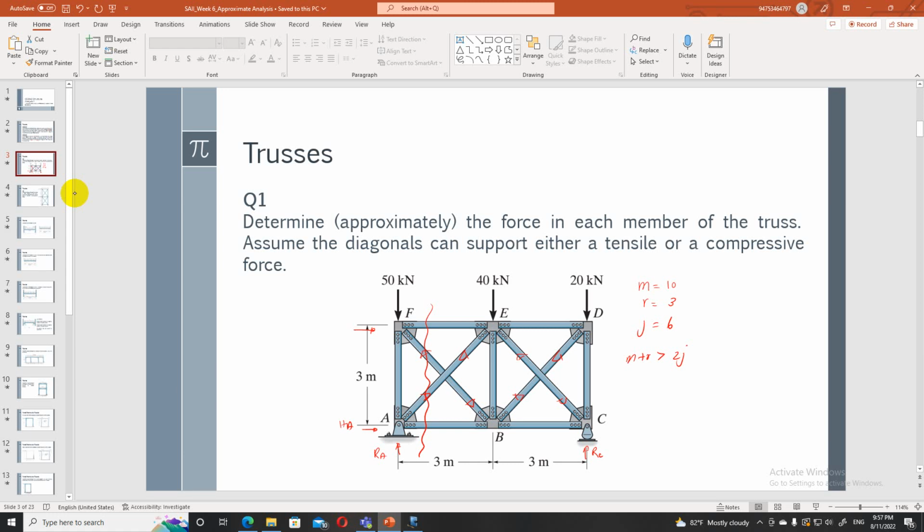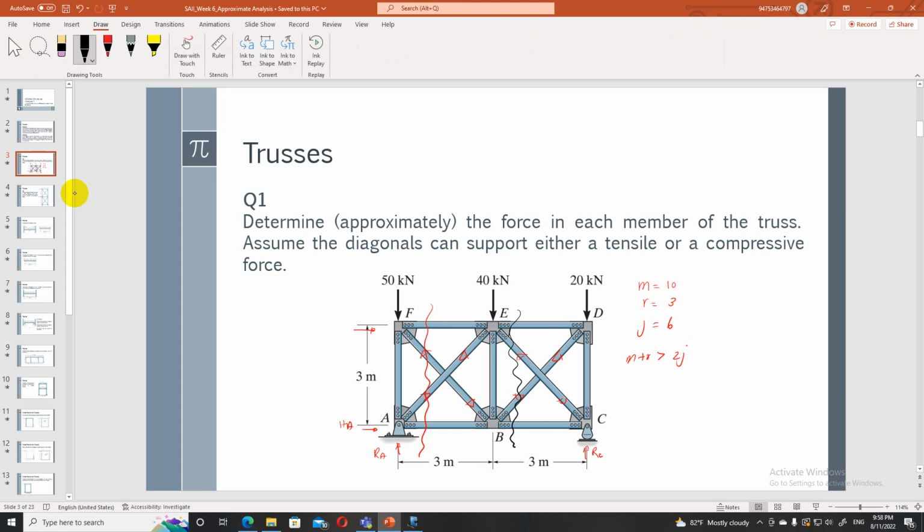The panel you can see. Now once you get these two member forces, you can take another shear force cut here and find these two members using the same method. So then all the diagonals are resolved, then other members can be resolved. So if you take this point, we can find these two members easily.